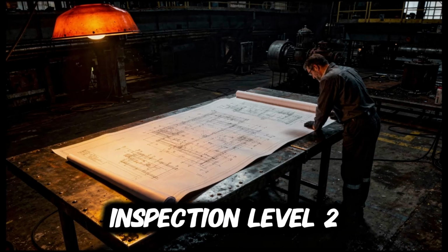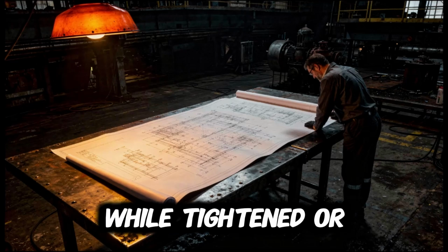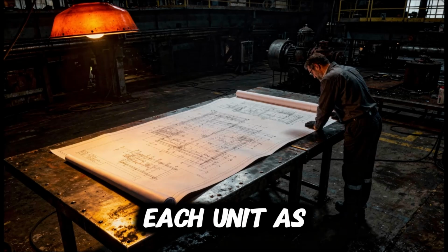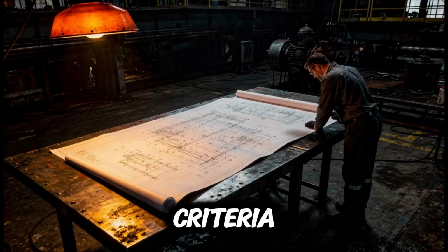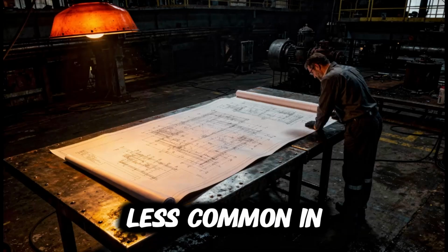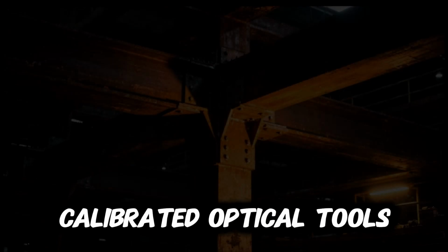General inspection, Level 2, is commonly applied for routine visual checks, while tightened or reduced levels adjust scrutiny based on process stability. Attribute sampling classifies each unit as conforming or non-conforming against predefined visual criteria, such as presence of surface cracks or dimensional out-of-tolerance conditions. Variable sampling, though less common in pure visual testing, may incorporate measured parameters like weld reinforcement height or corrosion depth when supported by calibrated optical tools.